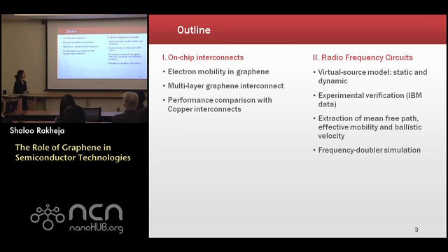In the second part of my talk, I'll go over a specific model that we call the virtual source model that I've developed for radio frequency circuits. It's a static transport model that is also supplemented by a dynamic charge partitioning model. We've done a lot of exhaustive experimental calibration with data from MIT, Columbia University, and also from IBM. In this talk, I'll be focusing on the new data that we got from IBM.